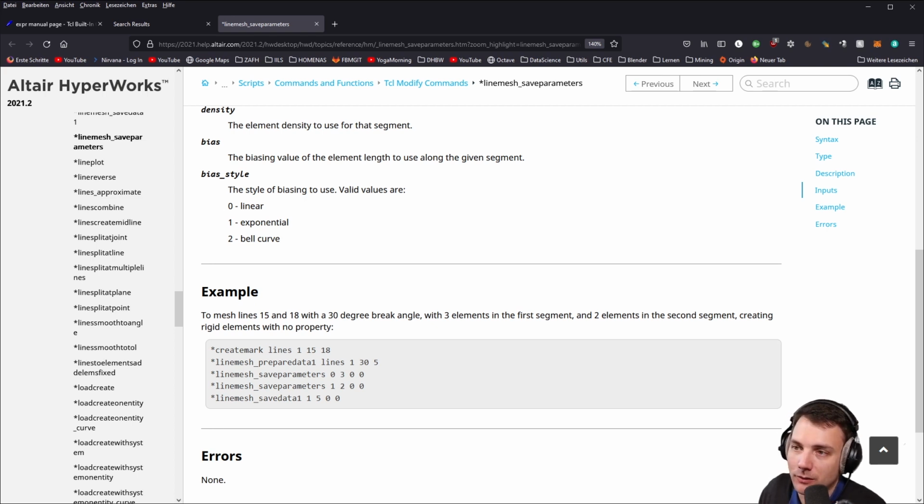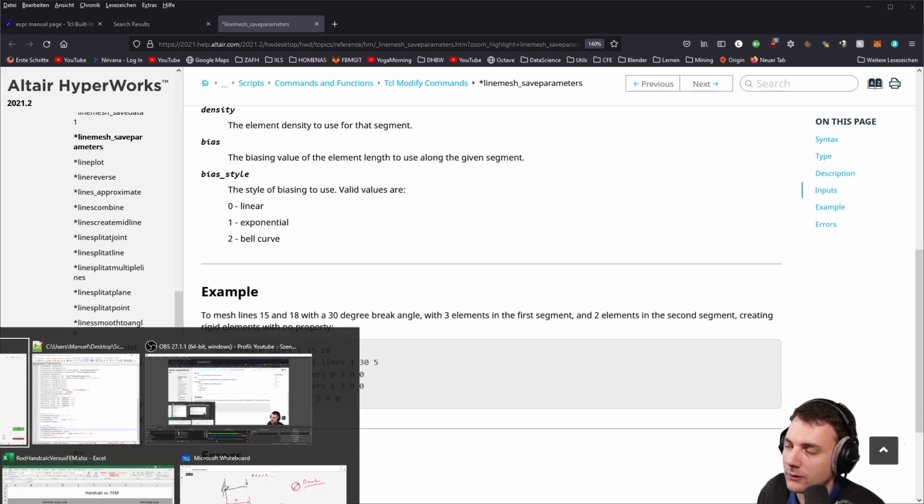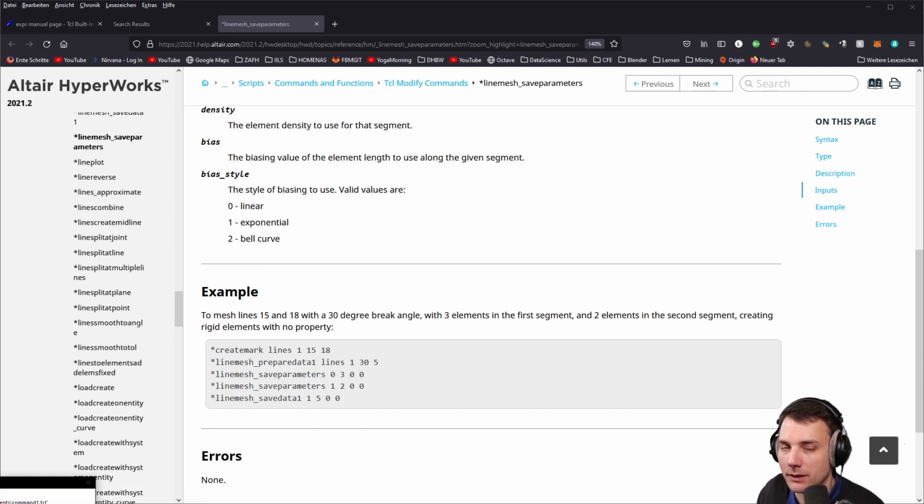Let's see how this goes. I will just make it once again. Line mesh. Select both lines. So 2 lines added. Element size is okay. No property, bar 2, mesh. Return. Let's see how this goes. And so you can also understand the behavior of Hypermesh a little bit more. So you see here, this comes only 1 time, and now you have 2 lines.